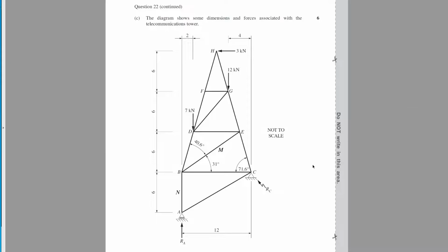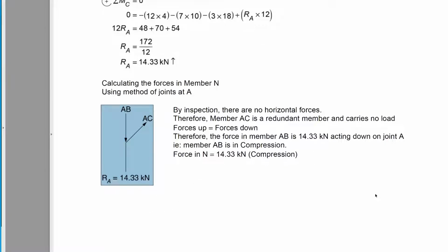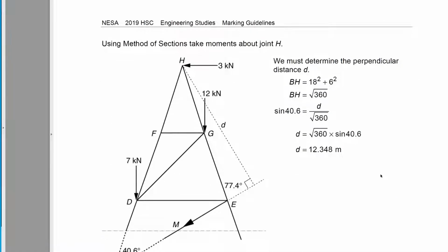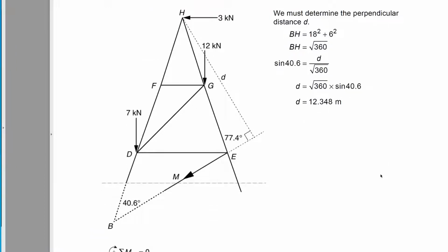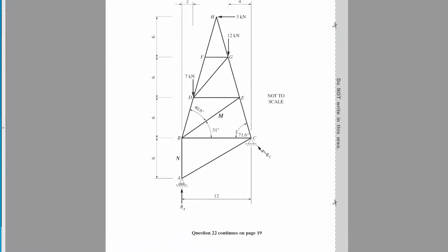If we look at the answers here, they're going to show us this value here. Now, you can use your trigonometry to do this. Ordinarily, I would just say, if you have a question like this, just draw the D and scale it. Draw that line out, get your set square out, extend BD, which is what we're calling M, extend this out here, and then run your set square along until it touches H, and then draw your perpendicular line. And then measure it to scale.